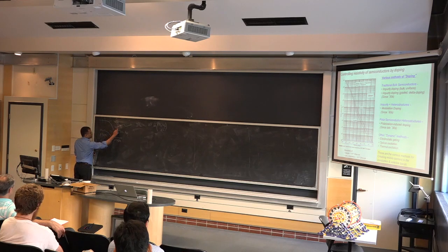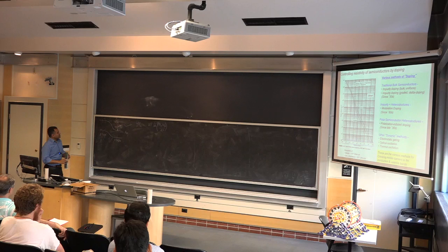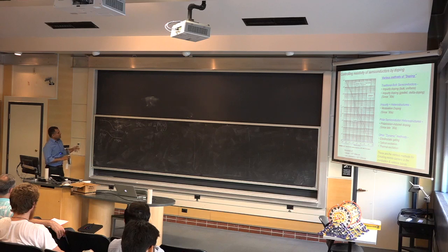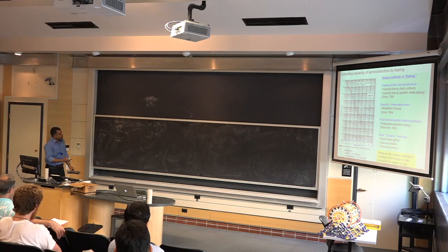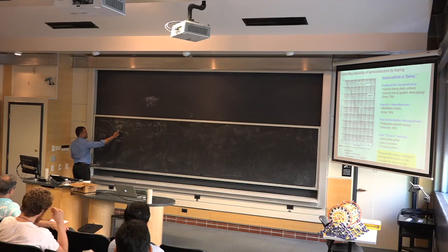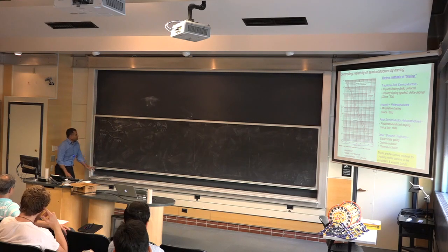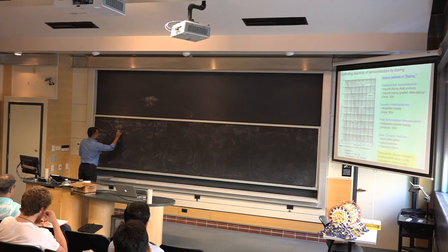We're going to now look at this sort of a junction in some detail, and we are going to look into electric fields, where are the charges, etc. And in that process, we're going to develop the idea of a band diagram. Now, one of the things I wanted to cover before we get into the building blocks is, once you put carriers in the bands, meaning I have lots of electrons in the conduction band here, lots of holes in the valence band here, I want to make sure we understand a couple of things. First, when I say I have an n-type semiconductor, I have electrons in the conduction band.